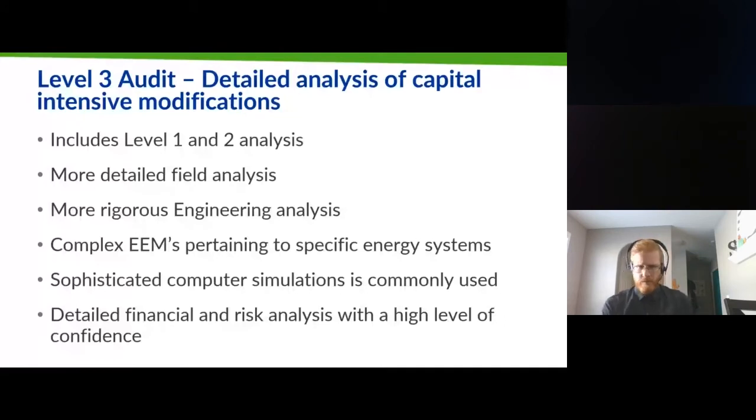It expands on the level 2 audit and includes everything from a level 1 and 2 audit, and it provides a dynamic model of energy use characteristics of both the existing facility and all the EEMs that were identified. The building model is calibrated using actual utility data to provide a realistic baseline for operating savings for proposed EEMs.